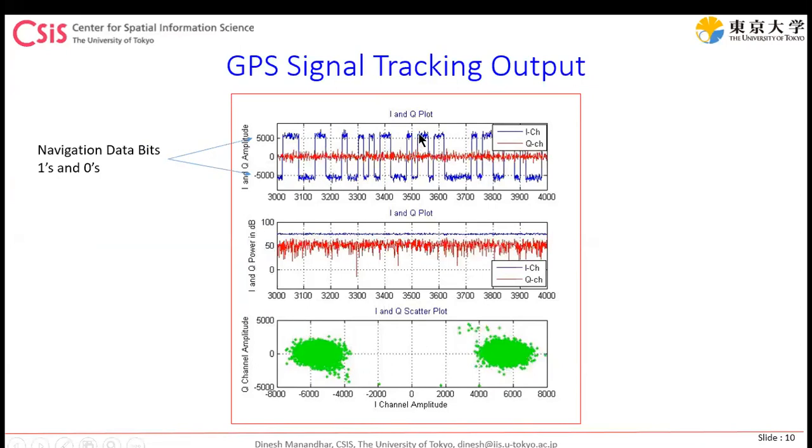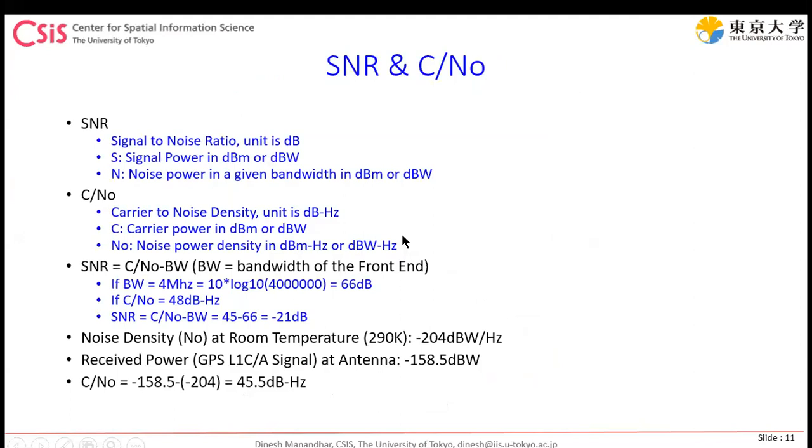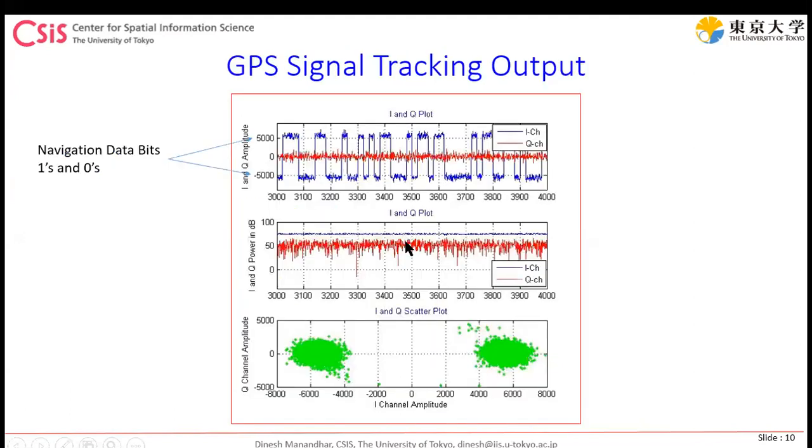And you compute the power from the blue dots. You see the noise here, the signal power, and this is the noise power. So you divide this, and you get the SNR, signal by noise. You see the signal, the blue, and the red is the noise, okay? And this one, again, you plot in a different way, so you get these two types of scatter. That's a BPSK. Okay?